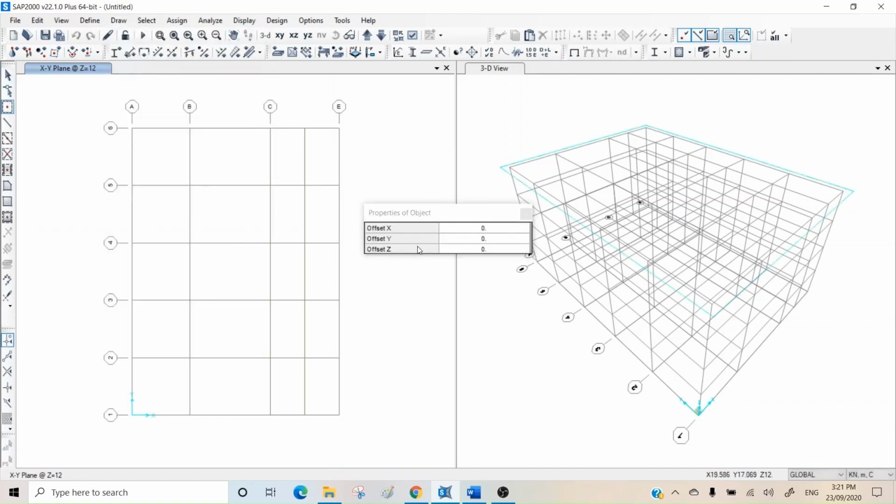When you draw a special joint, you can either just put it at the grid line. Yes, you can draw it here, but you have no idea of the orientation and distance. So to have this joint properly located where you want, you need to use the snap tools, and you need to use these spaces. For the snap tools, I just need to combine some features together because it's very hard to go for one of them without explaining the others. So snap tools here give you some options to pick some locations. I will draw some elements and then we can try them, but I'm showing you what's happening here.